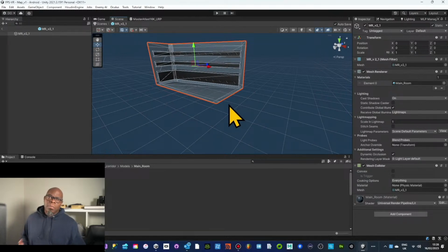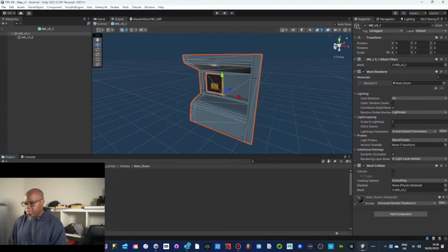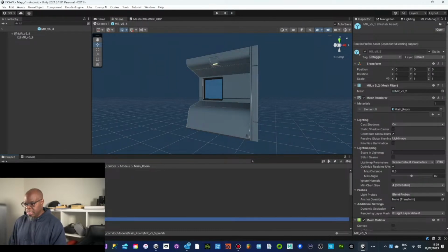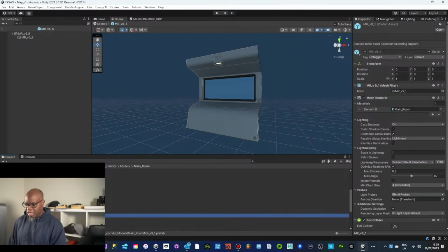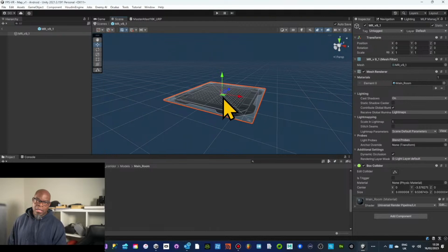It's just an asset. But in my instance, I'm taking the FBX from Unity and discovering what has been done in the authoring tool, which wouldn't be Unity, and trying to recreate it so that I can regenerate the scene in Houdini. So, we're looking at this here, and the asset, like I mentioned, has been raised, and for the majority of these, it has. And then for some of them, you'll find they're just sitting at 0 0, especially if it's just like a base mesh like this.